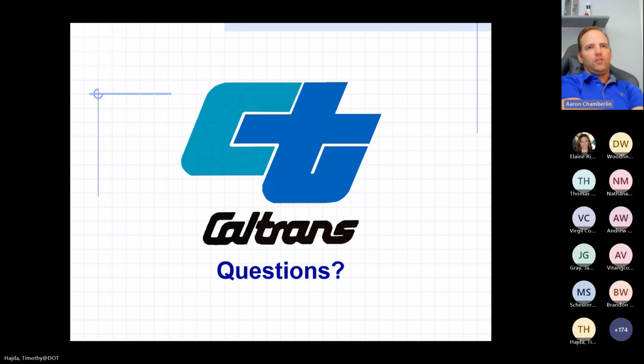Yep, another question just came in. Do you keep various point cloud data sets separate, or do you merge them for processing? And a follow-up question on top of that was, do you perform classification on those point clouds? We do keep them separate just because of the varying accuracies of each of those. But when we are extracting, we do have the ability to view all of them. So a little bit of both, but we don't actually merge the files themselves. For classification, we do carry out, for example, ground classification, which can help to eliminate vegetation if we're wanting to produce a bare earth DTM.